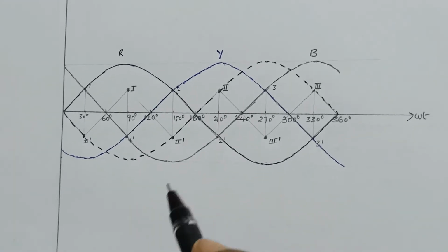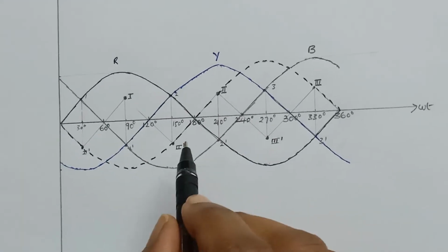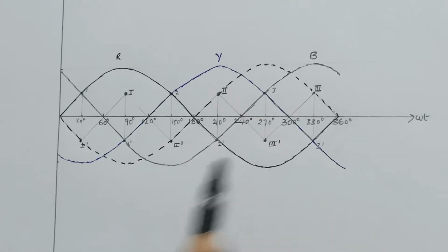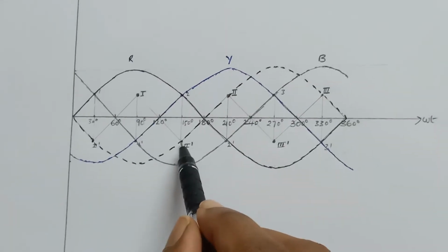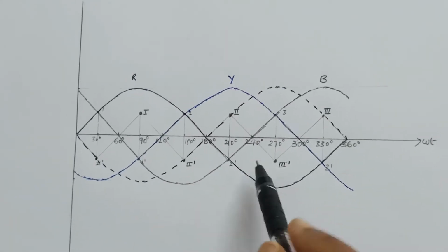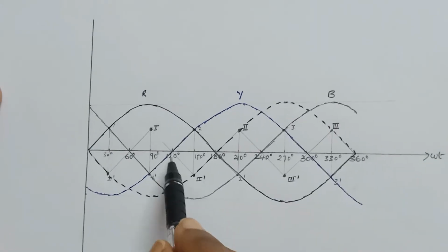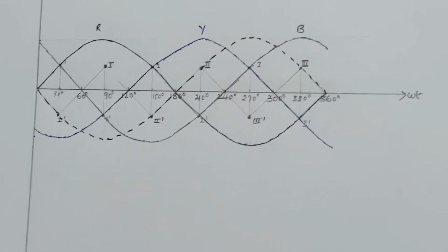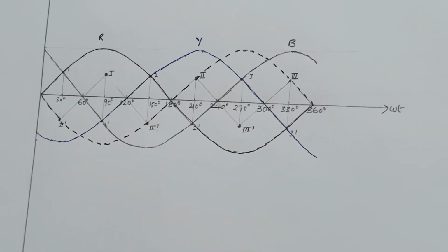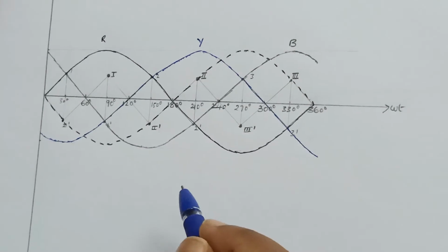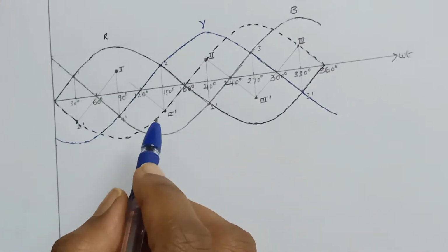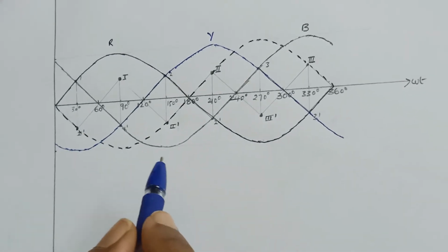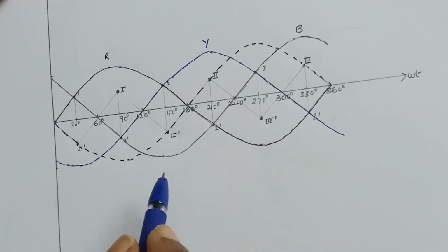Now let us concentrate on the second and third tops of the bottom or negative group triangles. Again, through a smooth sinusoid, join these two tops and extend its proceeding as well as preceding paths. So here also we will be using the color whatever we have used for constructing the B phase waveform. As we have taken blue color, let us also now consider the blue color, but use the dash line pattern to represent the waveform being constructed.